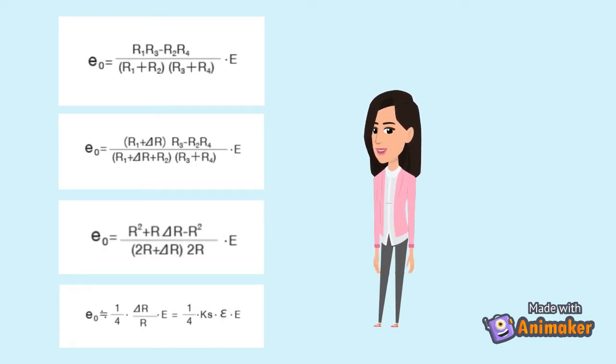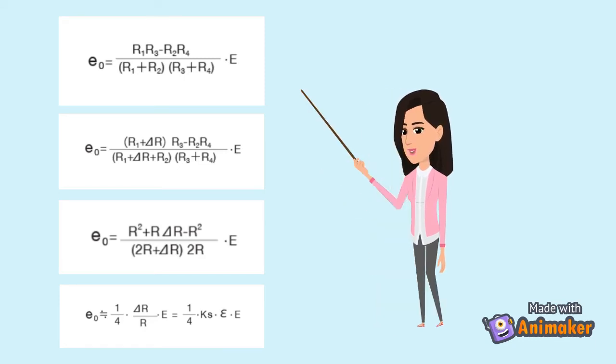Under these conditions, the bridge is said to be balanced. Any change in resistance in any arm of the bridge results in a non-zero output voltage. Therefore, if you replace R1 in the circuit with an active strain gauge, any change in the strain gauge resistance unbalances the bridge and produces a non-zero output voltage that is a function of strain.